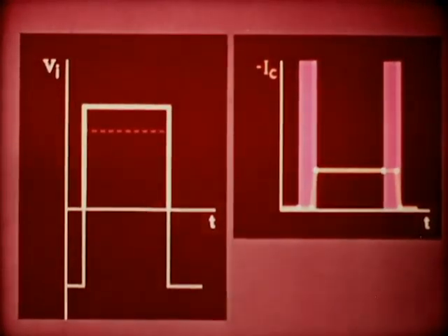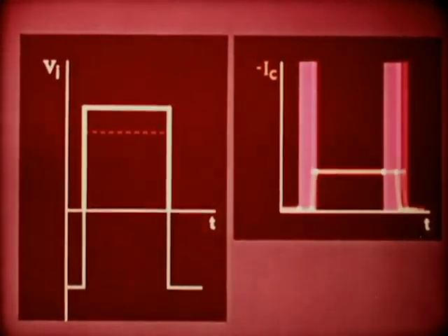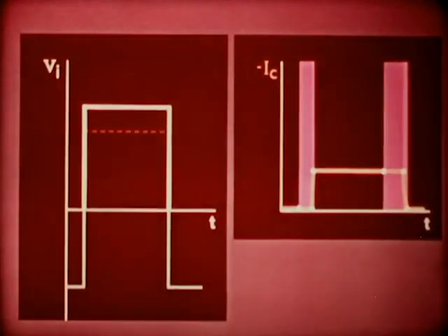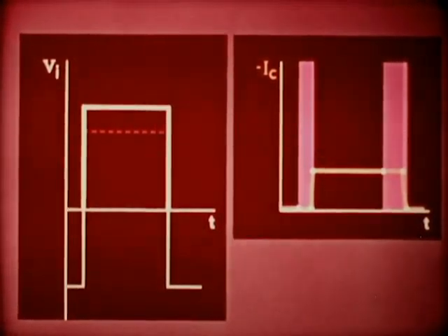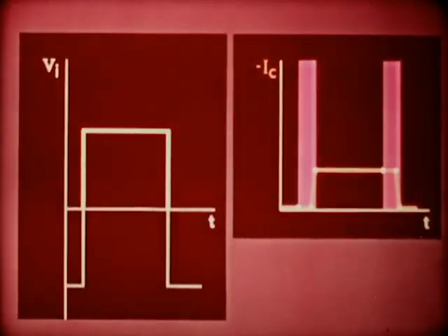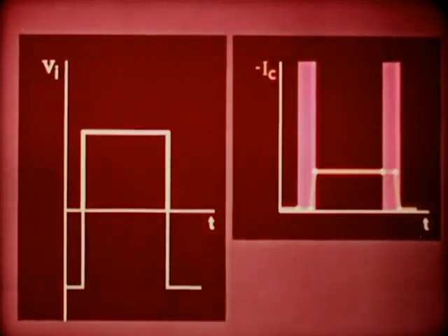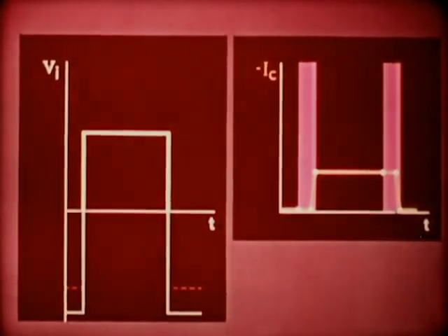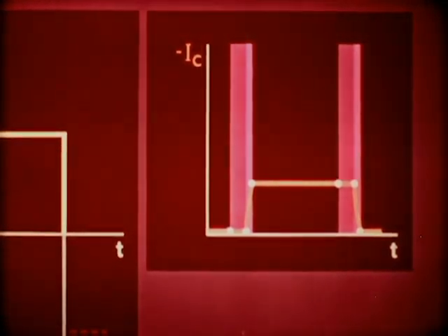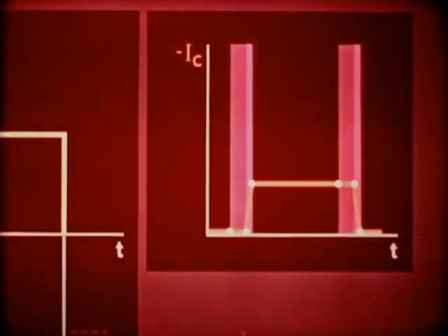So to reduce TR, it is sufficient to increase the saturation voltage. But then simultaneously TS will increase, because the amount of holes stored in the base has also increased. In the same way, to reduce TF, the transistor must be brought rapidly to cutoff. But in this case, because the emitter-base barrier region has become wider, the delay time, TD, increases.